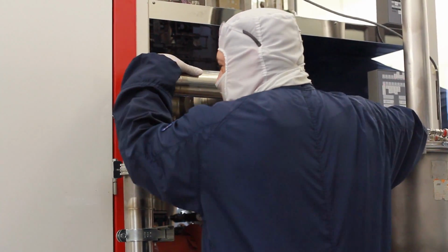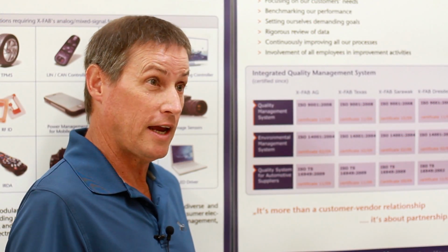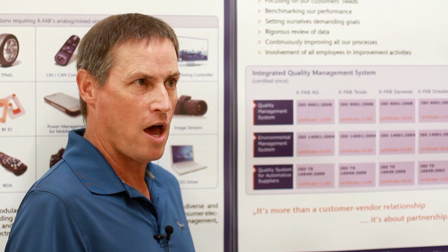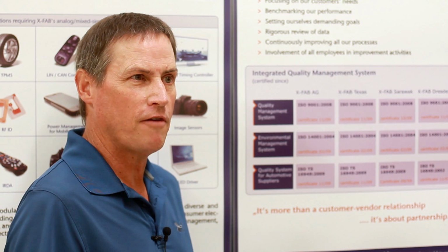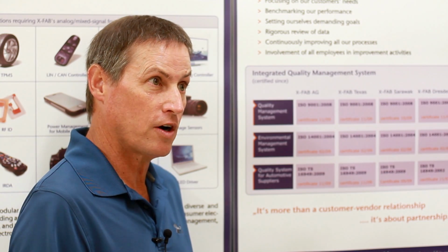Dynamic capacity models can be created, however, they take a lot of time and effort, and they also take a lot of effort to maintain the model even after it's been established, because every time you make a change in the process flow or in the equipment, you have to then go update the model. Also, validating that model is very difficult. It may take 6 to 12 months of real production to actually validate a dynamic model. And so they're not used very often because of the effort it takes to install, validate, and then maintain on an ongoing basis is very costly.